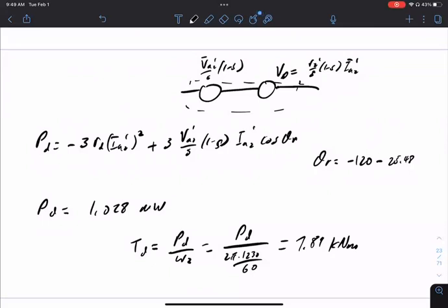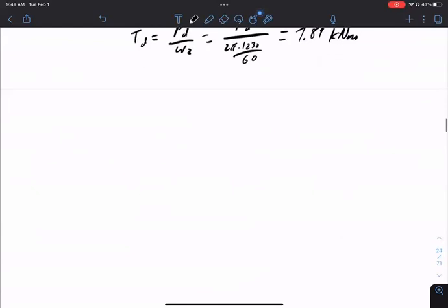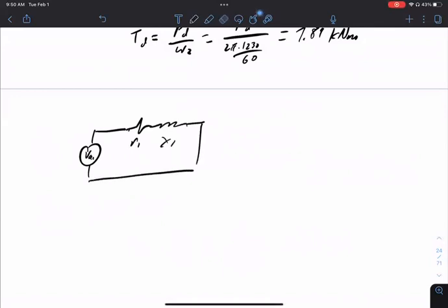So now let's compute the power to the stator. I want to now compute the power to the stator. Do I need to compute IA1? So now we sort of unroll the Thevenin equivalent circuit, VA1 here. You have IA2 coming in here. So the question is, what is IA1? How much current do I have left of IA1?